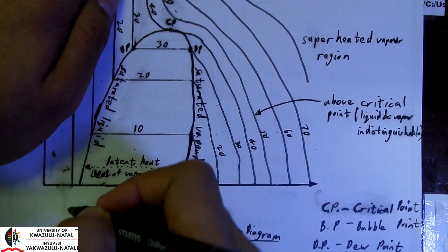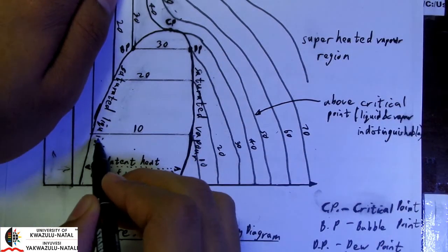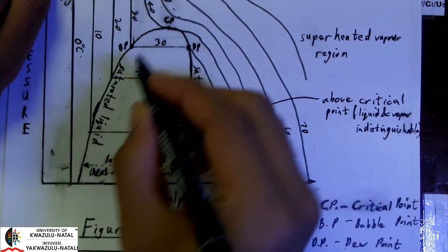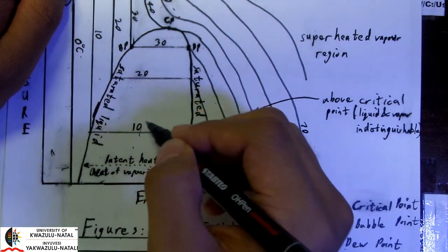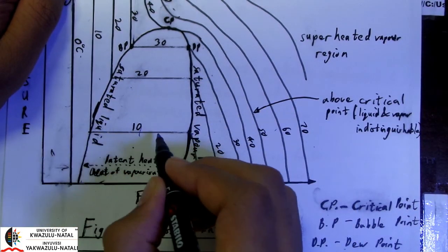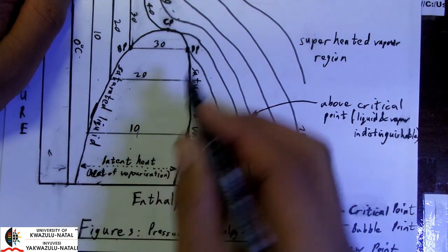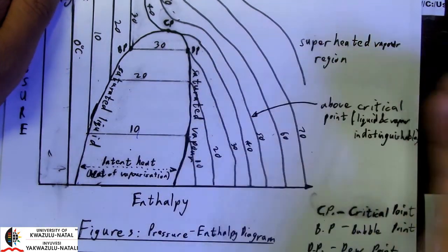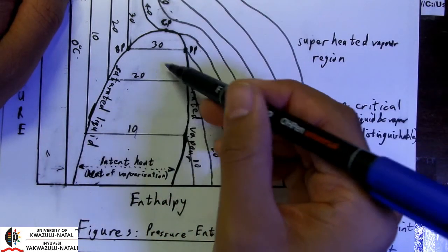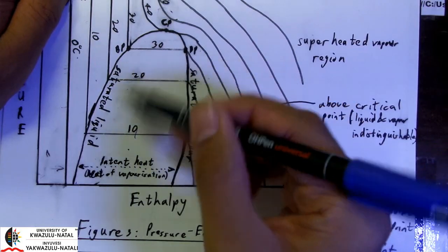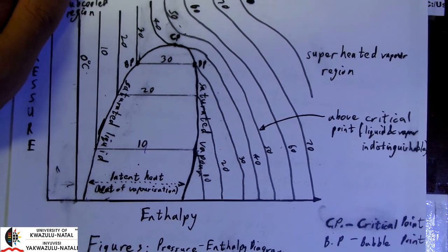However, since there is such a large difference between the saturated liquid and saturated vapor, we can infer that as we are nearer to the saturated liquid line, we will of course have more liquid than vapor. And as we progress to the saturated vapor line, we will obtain more vapor than liquid. And once we are at the saturated vapor line, there will only be vapor. But what if we are operating at the saturated point and we are using neither saturated liquid nor saturated vapor?